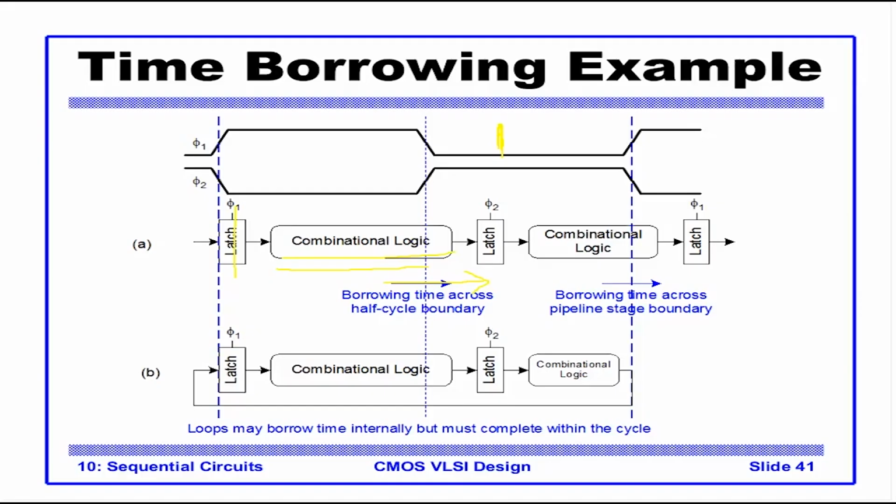Data directly goes to this third latch, and when it wants to capture this, the data should remain stable, let's say, somewhere around here. So even if this part of the circuit is slow and this part is fast, we made sure that the time is not wasted, and in fact is perfectly utilized.